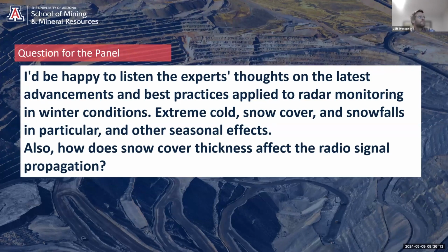Yeah. In my personal experience, most of the challenges when there is snow are during the melting season, because it's exactly when you have water infiltration, and this may trigger instabilities. And this is exactly when you may struggle with interpreting radar data, because the snow melting may generate some fake displacement on your radar map. So that's exactly when you would like to have good data.